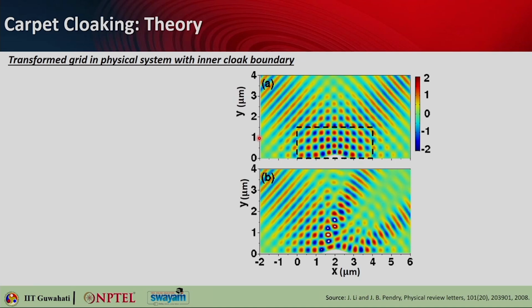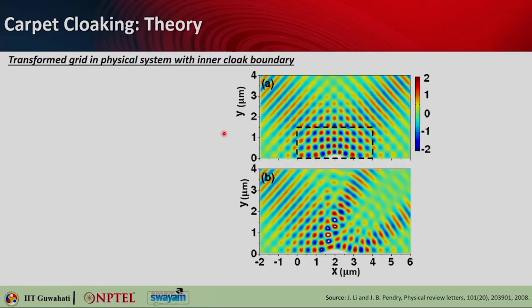So, in this case you can see the permittivity of the cloak varies from say 1.5 to 4.4, and this is a pretty doable range, because these values are ones which we can easily realize. And how can you make it? You can take a dielectric substrate and drill sub-wavelength holes of different sizes in the z direction of a silicon substrate, and that can give you these kinds of permittivity values according to the direction that you want. So, it actually makes it possible to realize.